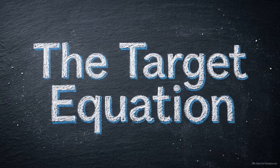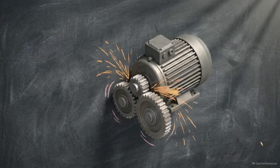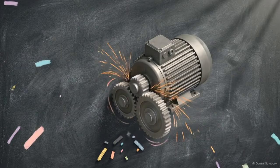Our destination is this specific equation: average power equals root mean square voltage times root mean square current times the cosine of phi. That final term, the cosine of phi, is known as the power factor. It is the critical variable introduced by alternating current. Defining the physical reality of the power factor allows us to determine the actual work a circuit performs.